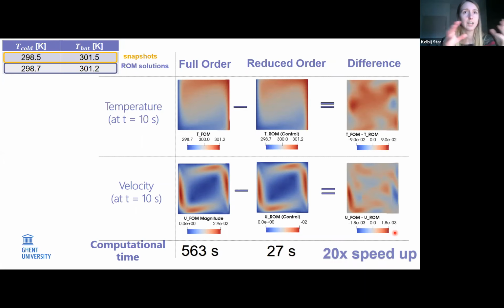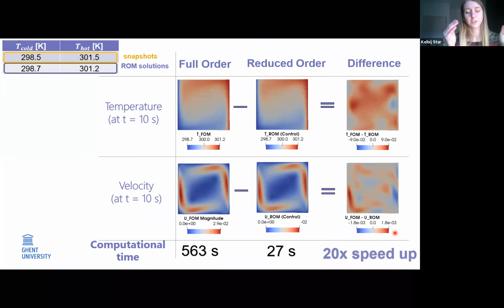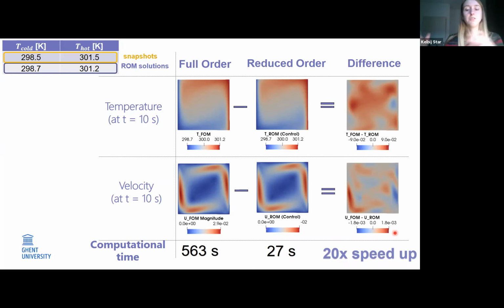But if I set up a reduced order model for one part of the regime and then another for another part of the regime, that is certainly something that is done. Especially if you work in a larger parameter range, you don't develop one reduced order model that can handle it all. You develop several reduced order models, and depending on where your parameters appear, in a certain regime or another, you take that reduced order model.